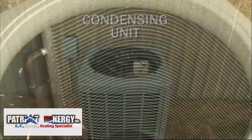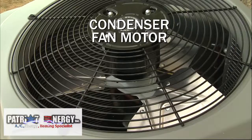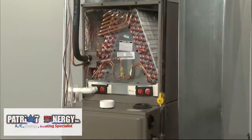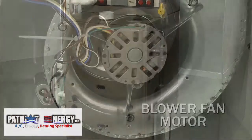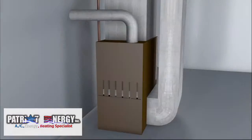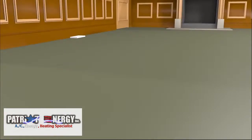home. The condensing unit contains the air conditioner condenser coils, the compressor, and the condenser fan motor. The evaporator coils, or cooling coils, are located inside the home and are mounted on top of a furnace or air handler. The furnace or air handler uses a circulation blower fan to draw air through the return vent, blow it past the evaporator coils, and force the air through the home's venting.